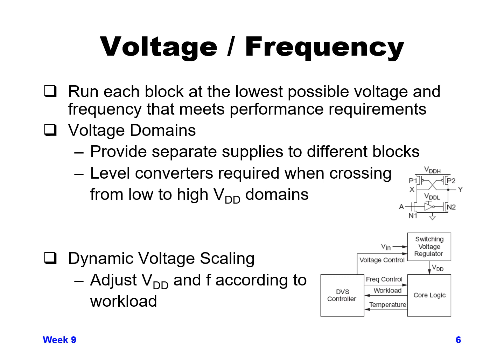So this is a really good technique to use if you have multiple voltage supplies that you can run in different areas of your chip. You can potentially run some areas at a lower voltage and a lower frequency if they're not as critical to your performance.